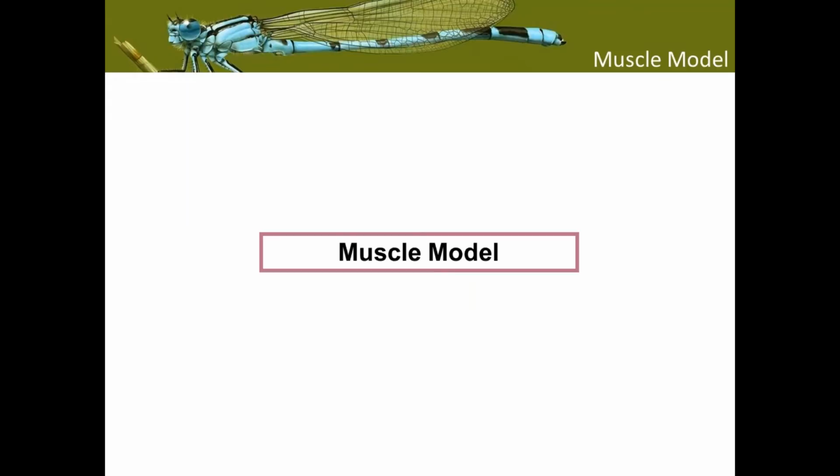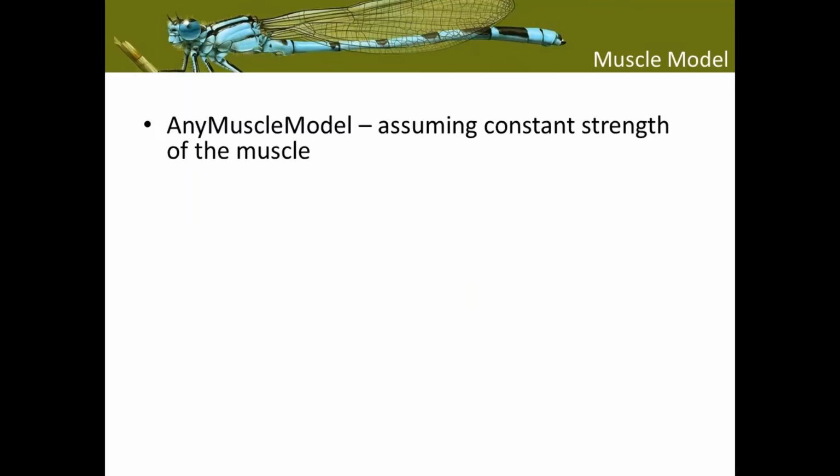The next step we needed to adjust is the muscle model, and as you might know, there are three different muscle models in the AnyBody Modeling System. There's a really simple model where you only need the initial force to set up the muscles, but of course it ignores cross-bridge binding, which is not a really physiological behavior.